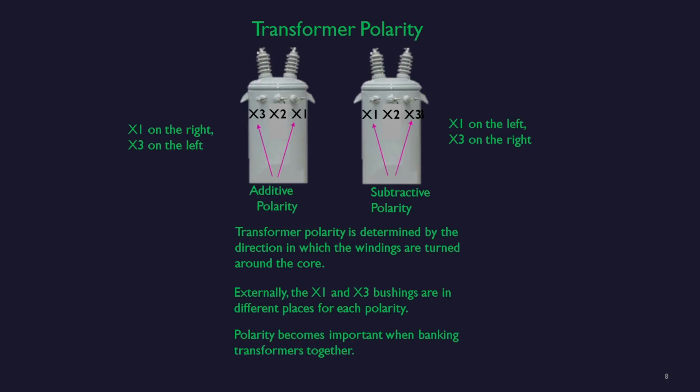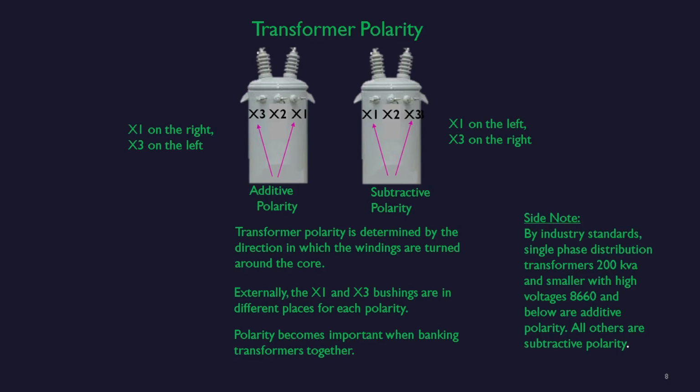Polarity becomes important when banking transformers together. On a side note, by industry standards, single-phase distribution transformers, 200 kVA and smaller, with high voltage of 8,660 volts and below, are additive polarity. All others are subtractive polarity.